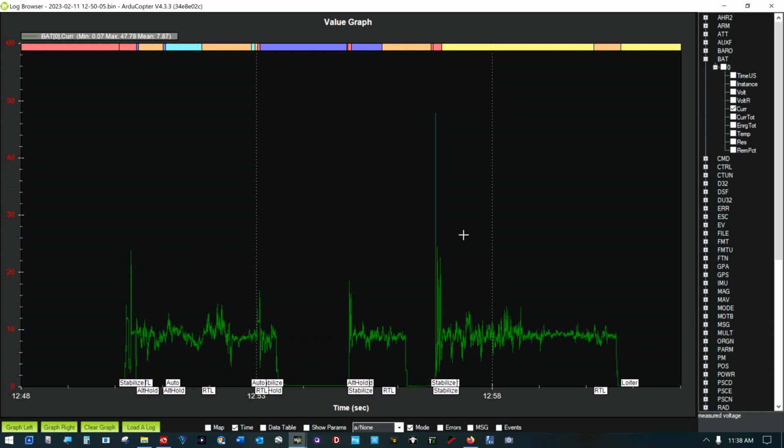So, at 55 amps per motor, what I was looking for there is, I didn't want to see a punch out here of greater than 55 times 4. In other words, I wanted to know that if I go to full throttle, I wasn't going to make the little magic smoke come out of my ESC. It'll probably handle more than 55 momentarily, but I don't want to play with that. So that kind of narrows it down.